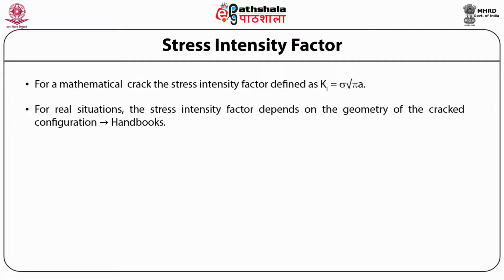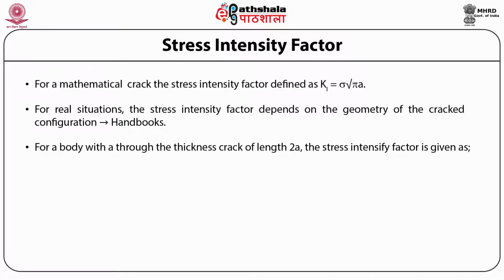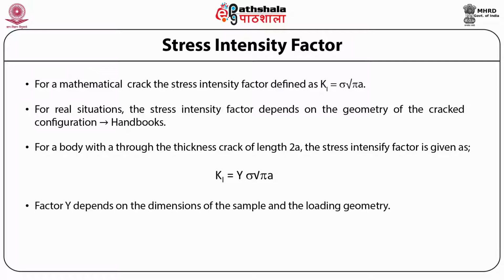The stress intensity factors for some common geometries are also available. For others, several approaches are available, some of which may be quite time consuming. So, for a body with a through the thickness crack of length 2a, the stress intensity factor is given by Ki equals Y multiplied by sigma multiplied by root of pi a, where Y is a factor which depends on the dimensions of the sample and the loading geometry.